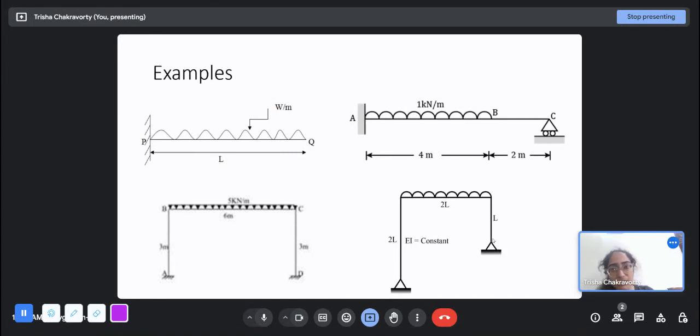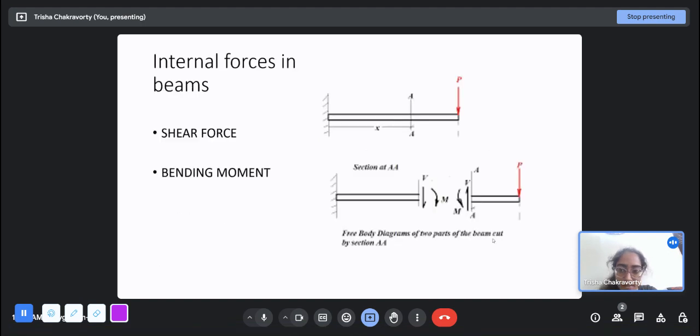But that is what we want. We want a structure to fail in stages to give warnings. That is why indeterminacy is very important in a structure. And in phase one, we look at the analysis of determinate structures, which is much easier to analyze. But in the real world, we mostly work with indeterminate structures.